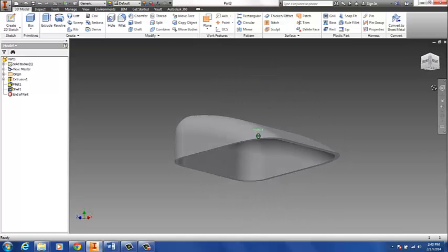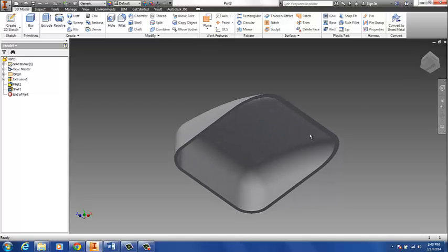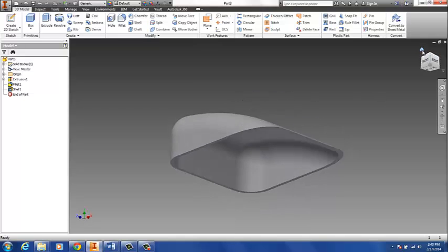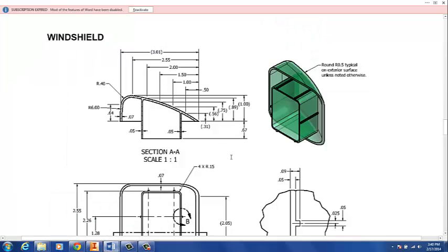All right, so what it's done is, starting from that bottom face, it's basically dug out all the material to a thickness of 0.07. Okay, the next thing we need to do is add this connector piece here. There are different ways to do that. It's essentially a rectangle with some fillets on it that's going to get extruded into our piece.